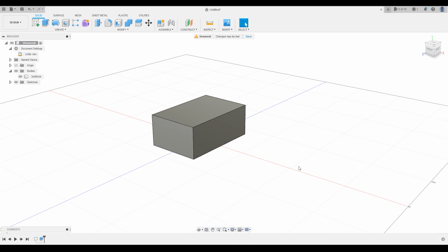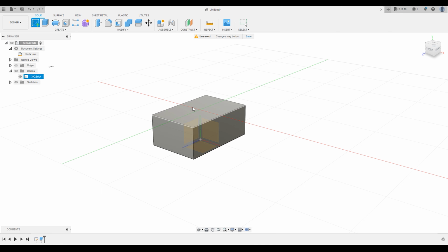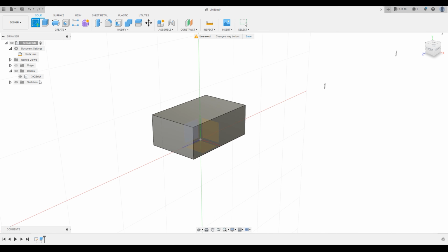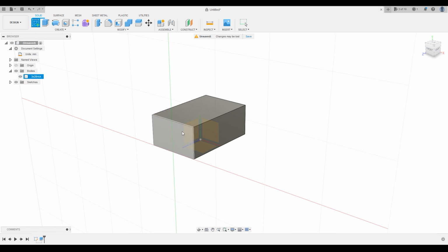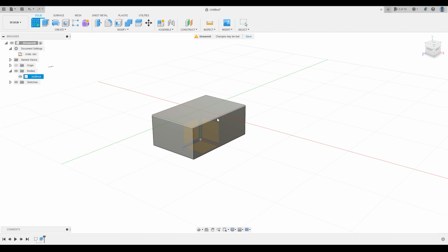Great. So we've got a box, we've got a 3D object, but it's not really a construction brick yet because it's missing its studs. So we're going to go through that same process again to create the studs. I'm going to create a 2D sketch, and then I'm going to extrude it in 3D space. So let's do that. Click here to create your 2D sketch, and now you can see I've got some additional options. Not only could I select those planes I had originally, which I can select either in the 3D environment or from the drop-down here, but I can also select any 2-dimensional face inside of the environment.